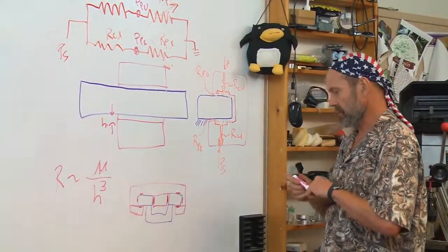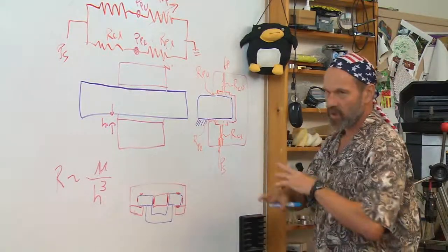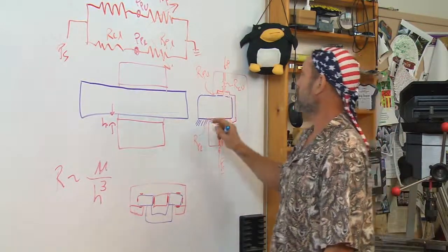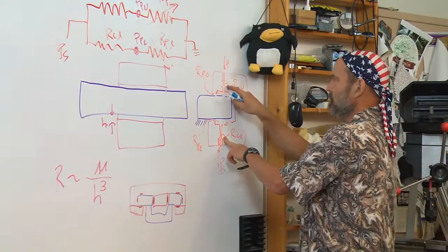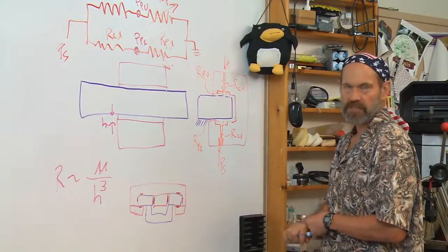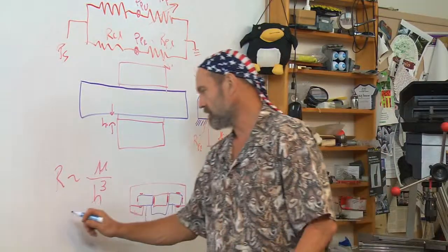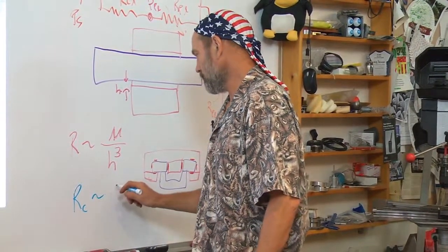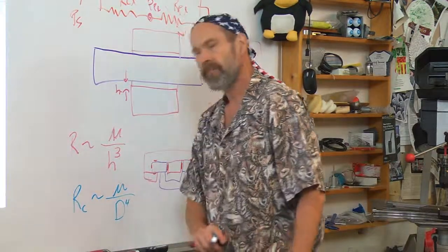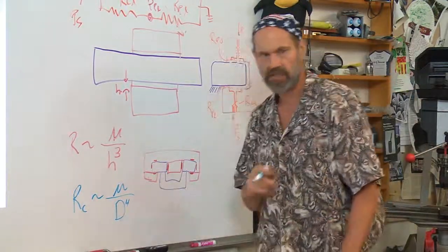And it turns out that to make this a stable, well-behaved system, when it's normally sitting with this gap equal to that gap, no loads, you want the compensating resistances to be equal and also equal to that bearing gap. But if you make the compensation resistance just a simple capillary, a small thin tube, the resistance of the capillary tube goes like viscosity of fluid over the diameter of the capillary to the fourth power. So the smallest variation in the diameter of that capillary can cause a huge swing in the resistance.